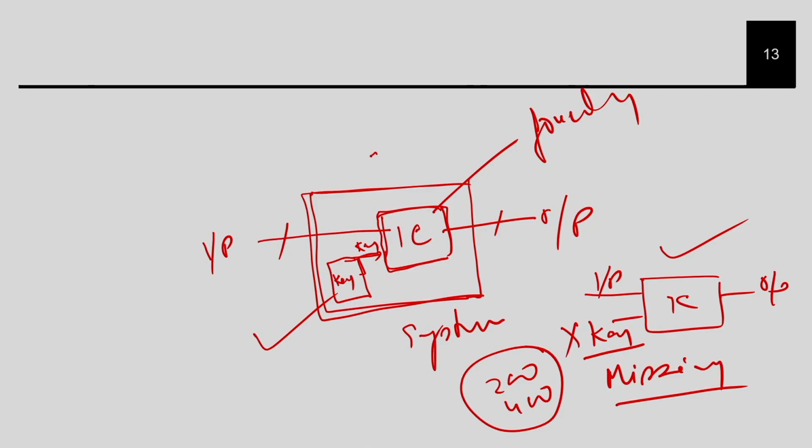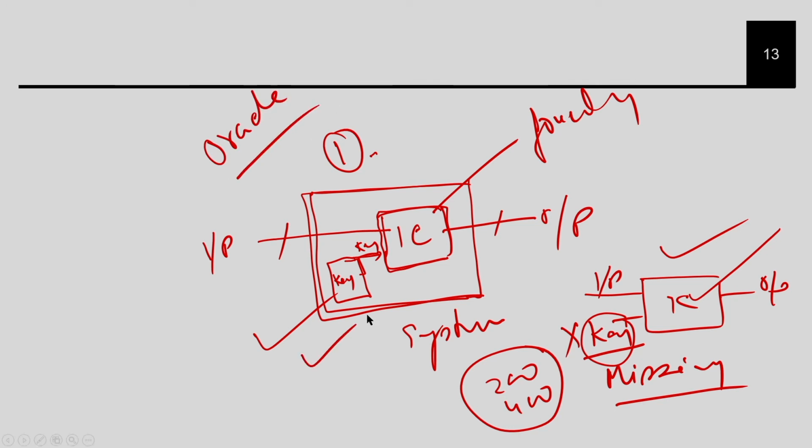once you have this locking, attackers don't sit idle, right. They try to see, if you have this key, can I extract the key, because I know the internal circuit, the netlist of the circuit, and I can buy one copy of this from the market, the genuine IC. That is called an oracle, right. So, I will buy one genuine IC from the market, so that if I give an input, I know what the correct output is. I cannot extract the key directly, but the actual correct input-output functionality I can get from the oracle, right. So, now I have the internals of this. By analyzing and checking the actual output, I can probably extract some of the key, right. So, that was the attack technique.